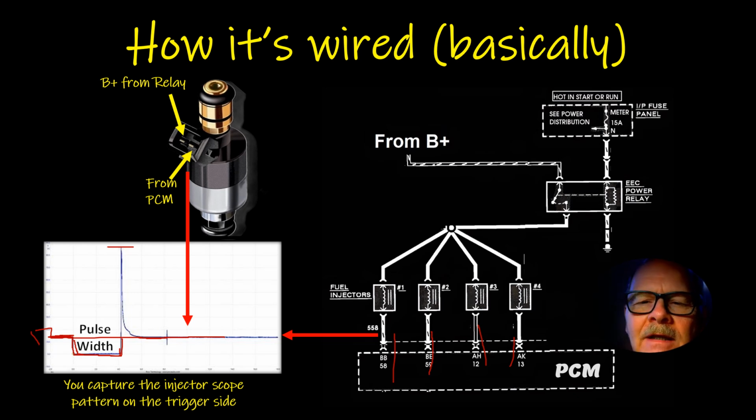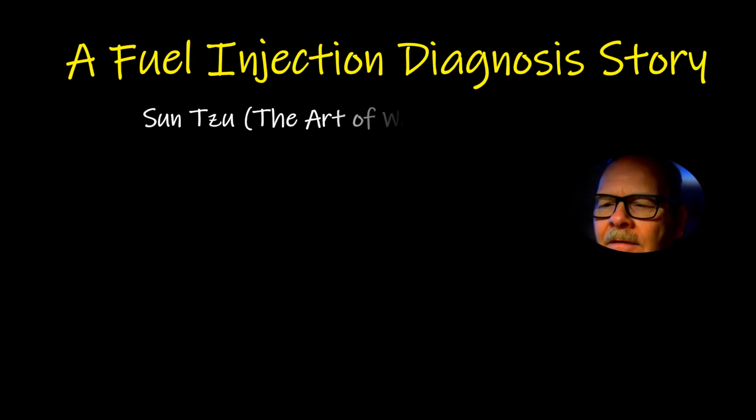And you'll see it. If you ever have that pulse width and you're reading it on a scope, and this is a scope pattern I'm showing you, and you snap the throttle, you'll see this thing get wider instantaneously. I had that fuel injection board that I built that I showed pictures of on here before, where you had LEDs connected to the injectors and all that, and it had a crank sensor and the engine controller all hooked up. You could measure that pulse width using a scope on that board of those injectors and pull that throttle open, and that pulse width would spread out because it thought it was squirting fuel, but it didn't have any way of knowing it wasn't on that little board that I built.